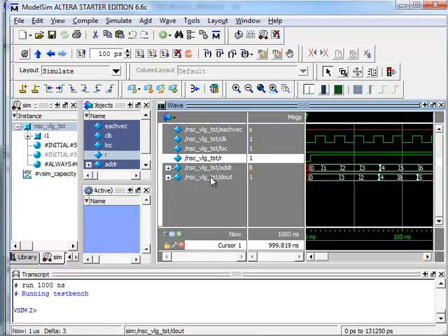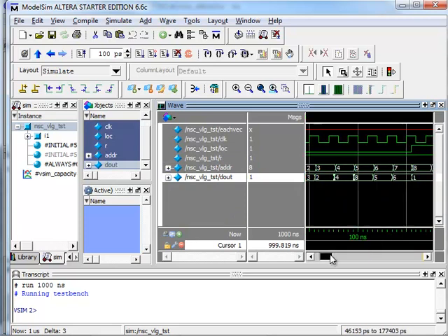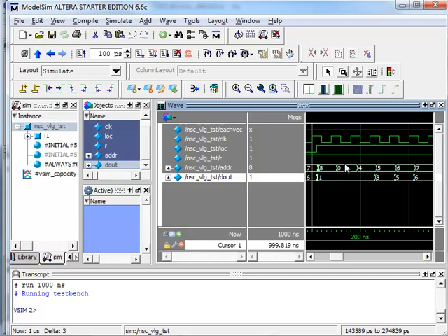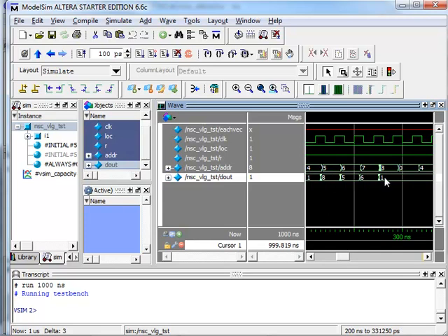As a result, looking at the data that's being output, after a few cycles of going through that jump conditional, you immediately see digits coming out, 324, 8561. At this point, the local pin goes high, saying this is a local number. So after jumping back to the beginning of the program, we now just get an 8561 coming out of our state machine. So that shows you that the simulation demonstrates that this is working properly.